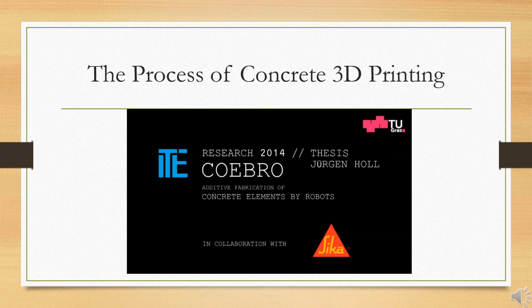Of course, this video has just presented to us the process of 3D printing. Before this part of the process, there is the process of mixing the ingredients together, which are, as I mentioned before, the reinforcing ingredient, the adhesive ingredient, the hydrator, and of course the cement, sand, and water all together. And then the mixture is fed into the 3D printer.